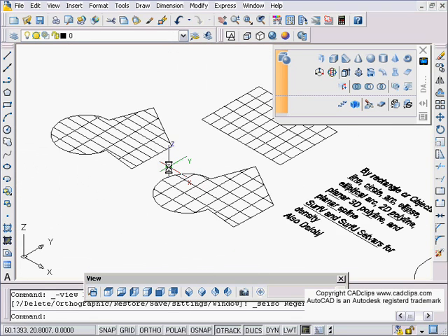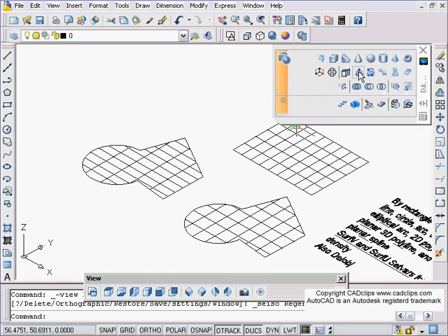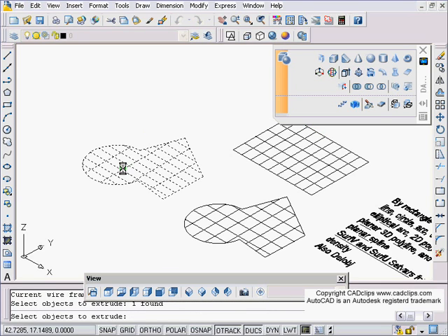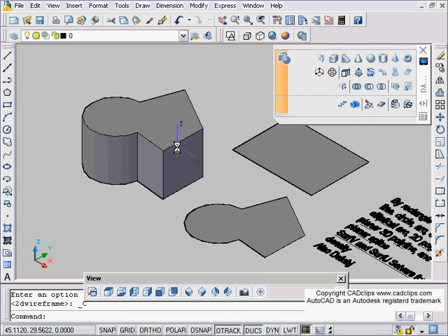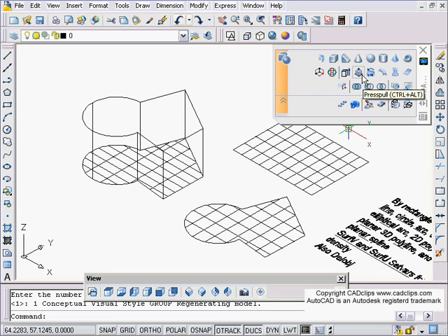And that's a surface, and we can go look at that in 3D. Can we do a push-pull on a surface? Doesn't appear we can. Let's just make sure. No, let's do an extrude instead. Aha, extrude we can. Go back to our visual styles. So we can extrude a surface. From what I'm discovering, we cannot push-pull a surface. Or press pull. I always say push pull.